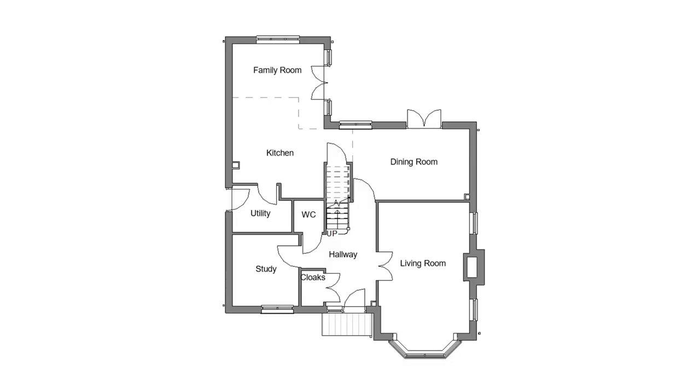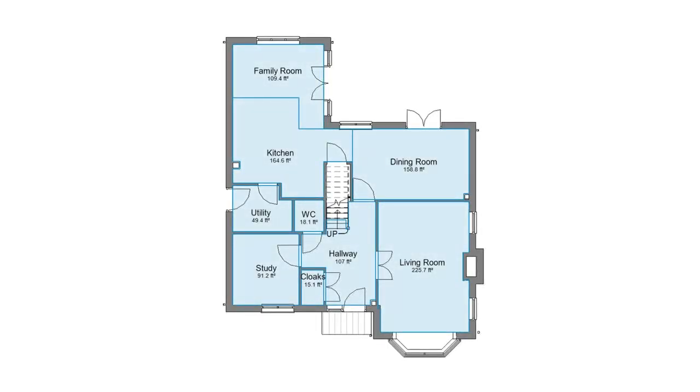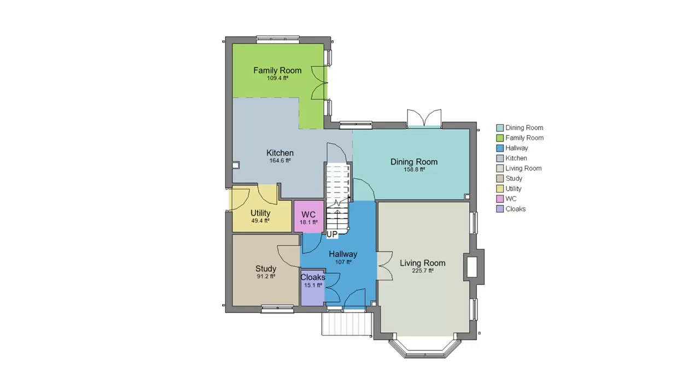When designing a building, we think about the rooms that we need to create, such as kitchens, living rooms, bedrooms, offices or classrooms. And we model the objects that will enclose those rooms, such as the walls, doors, floors and roofs. And the room is the object that represents that enclosed space. It calculates its dimensions, such as the area and volume, and allows us to assign information such as a name, number, finishes or departments. And they can also be used to locate other objects that are able to detect the room that they inhabit.